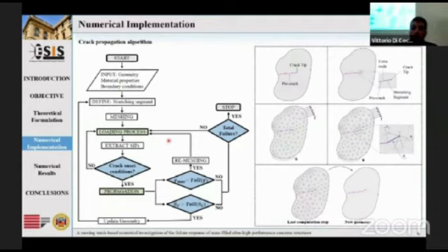So the moving mesh advances the crack tip to simulate the propagation. During the propagation, the elements around the crack tip are distorted because of the mesh motion, and remeshing events occur exclusively when the quality of the mesh is compromised.